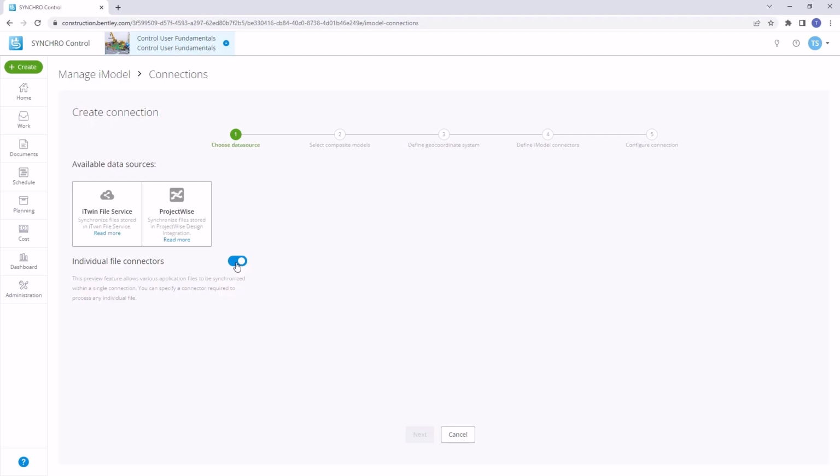In some scenarios, separate connections are intentionally created based on disciplines like mechanical, electrical, or structural. This way, if specific discipline-related design files are updated, individual connections can be modified instead of altering a single large connection. This practice can save time, especially in larger projects.